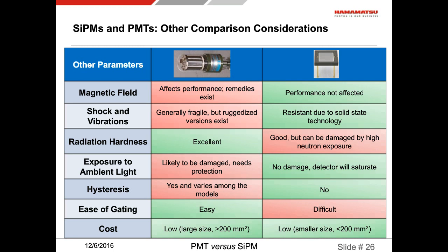PMTs can be fragile, after all, they're made of glass. However, ruggedized versions do exist. In fact, in oil logging, we use PMTs for the detection. SiPMs, because of solid-state technology and smaller size, are more resistant to shock and vibration. Radiation hardness of PMTs is excellent. It's very difficult to hurt a PMT with beams of protons or neutrons or electrons. For SiPMs, it's good. However, there is still